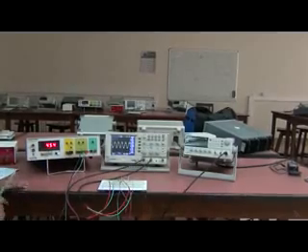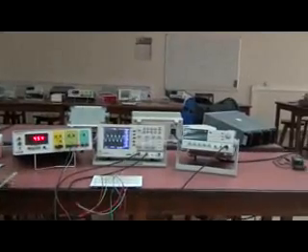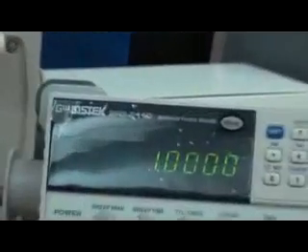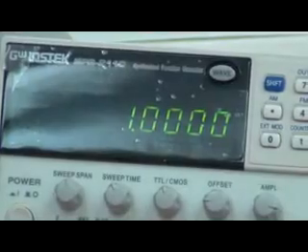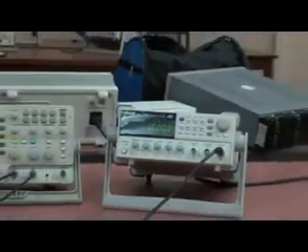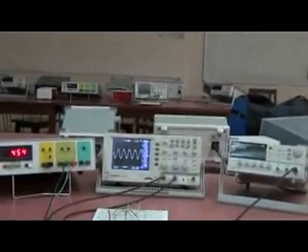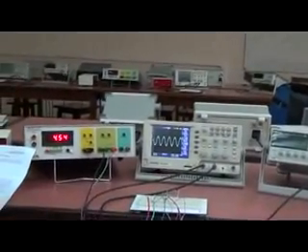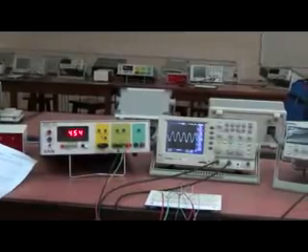Here for this clipper we are giving an input signal from the function generator. The value for the frequency is 1 kHz, a sinusoidal signal, and the peak to peak voltage for the input signal is 15 volt. Now, as shown in the diagram, we have connected the first switch, that is AD. The switch A dash D dash is open.